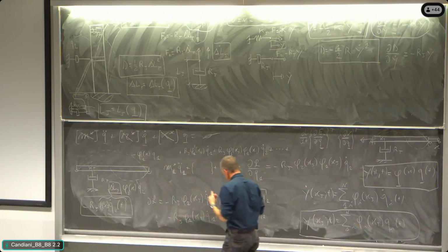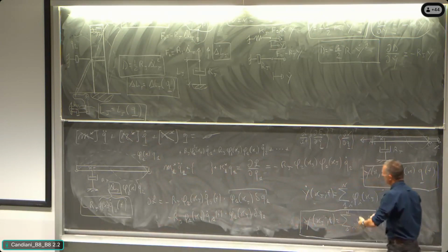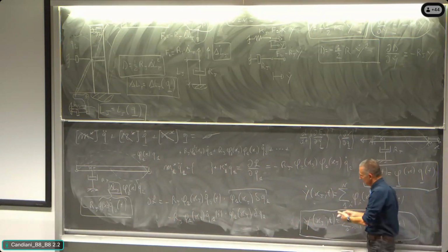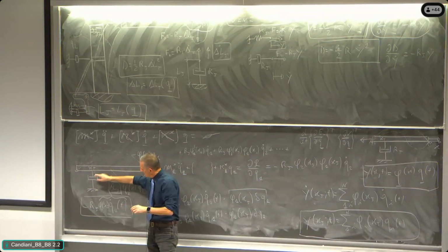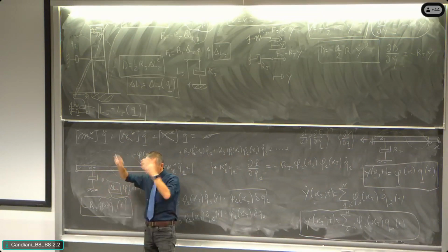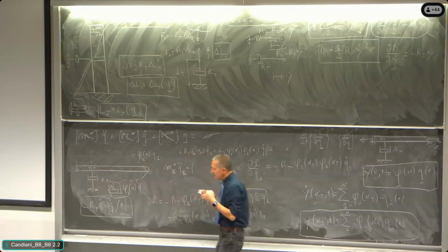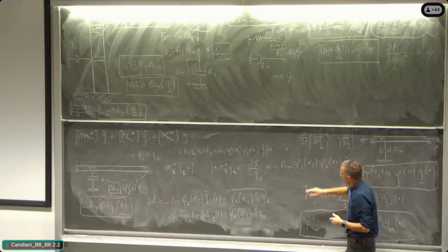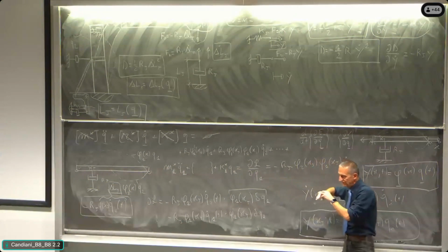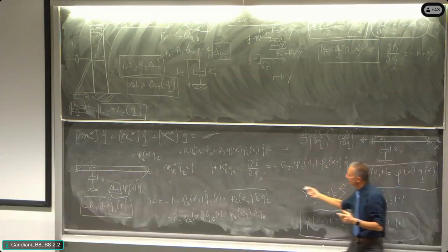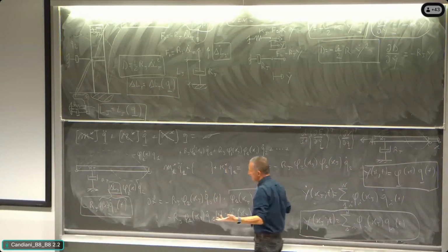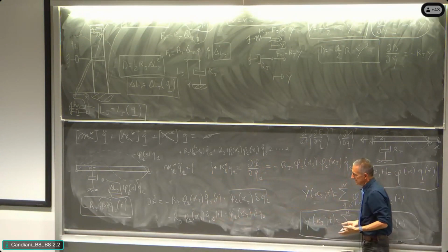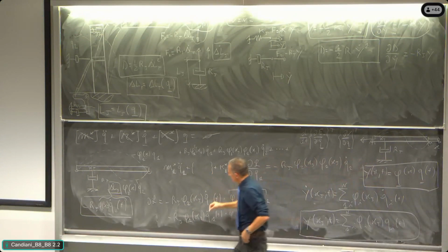For the damper, I am taking the derivative with respect to Q1 of the virtual work associated to the forces that are acting, and the forces are given by the elongation velocity associated to all the modes altogether. We take the derivative of the work done by the virtual displacement where I am moving just Q1. And so I am doing like that.